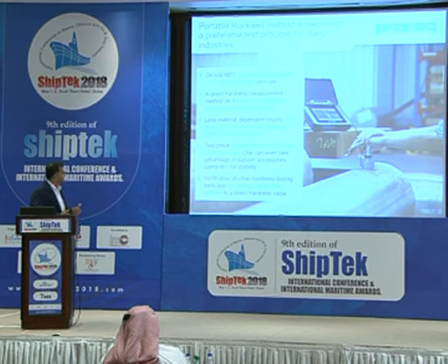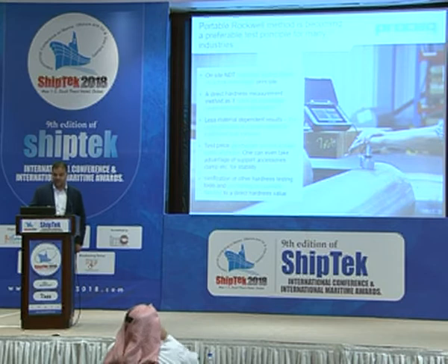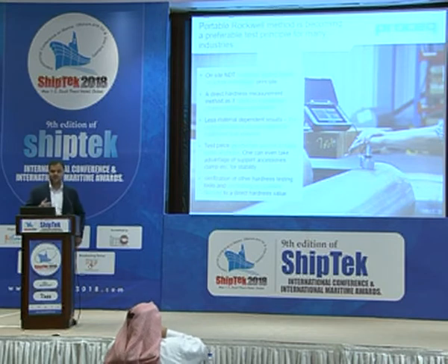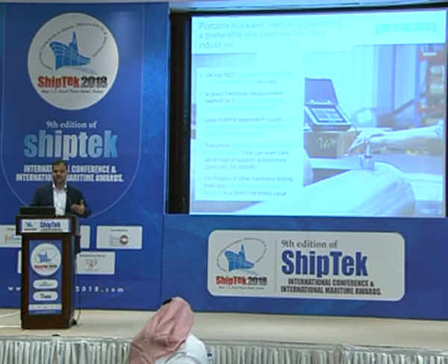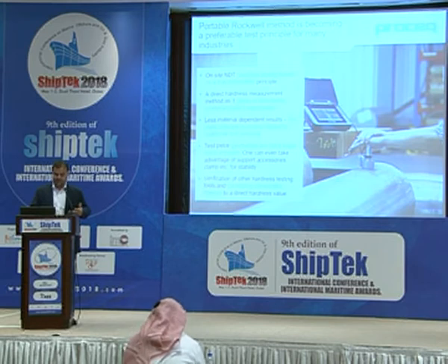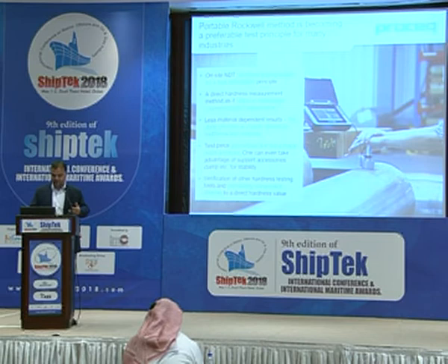On-site NDT hardness testing based on true indentation. So it's not a comparator, it's a true indentation, like a direct hardness measurement. It relies on indentation, which is based basically on the material's plastic properties, and it's independent of material, of course. And test piece geometries are not a major issue.